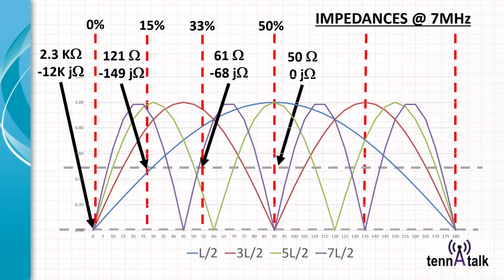So now, here's a way to look at standing waves and loading points and matching up impedances to an off-center fed dipole, for example, the extreme case of which is end-fed, as you'll see in a moment. Let's imagine a 40-meter half-wave antenna from here to here, and the 40-meter standing current wave, we're measuring current now, the standing wave is this blue arc.